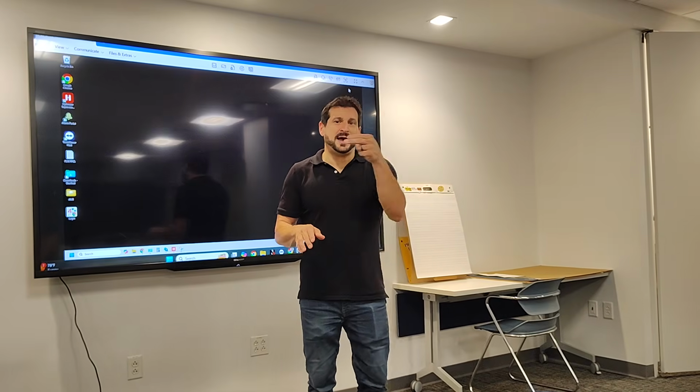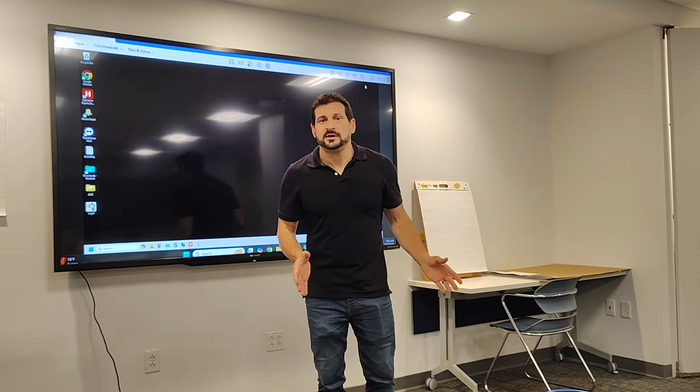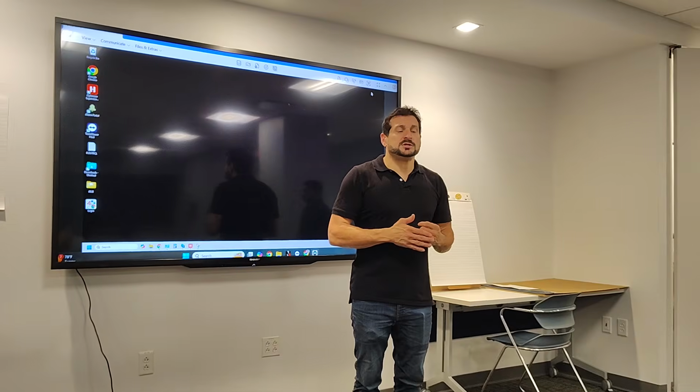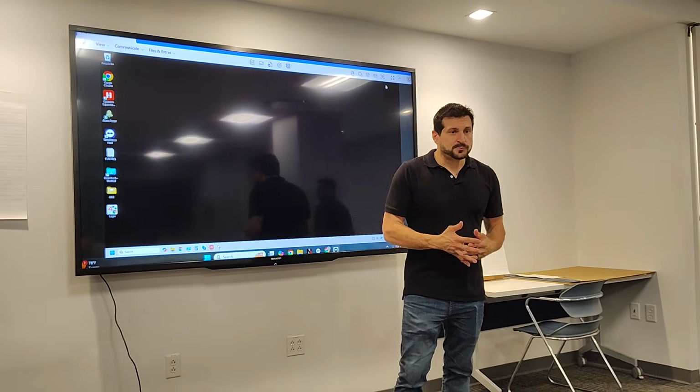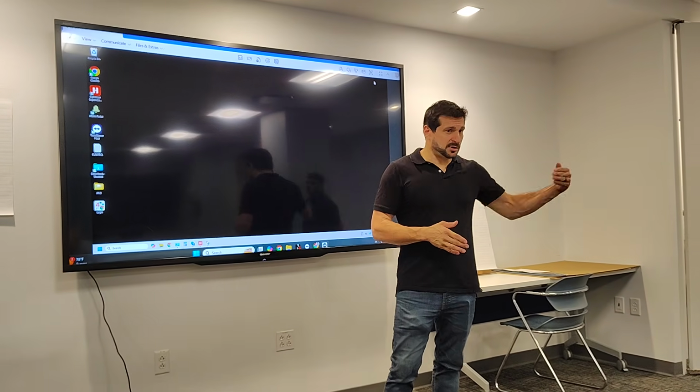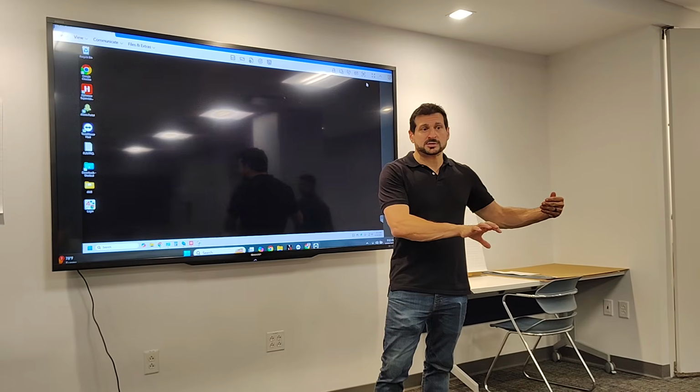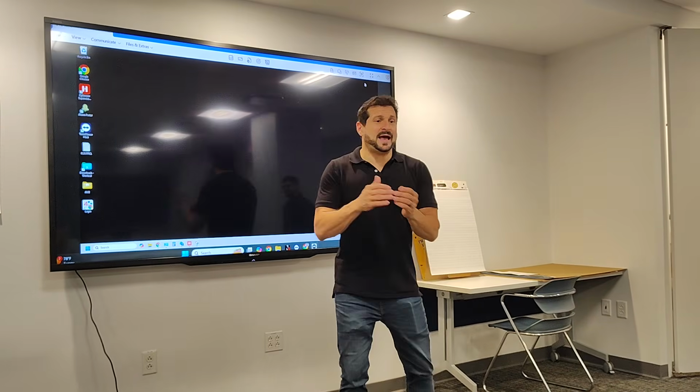Now the next one, outputs. That's a little bit different. Outputs is what the BMS is going to do in the building, right? So measured values are inputs. Virtual points are set points, things like that. And then outputs are the physical changes that a controller does to the building.